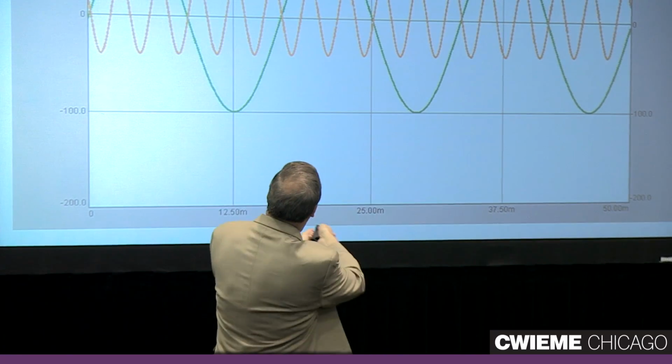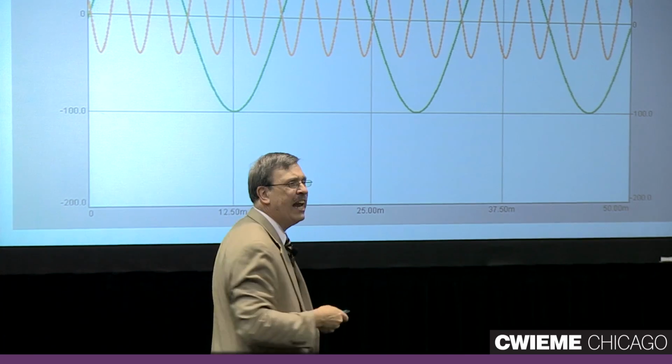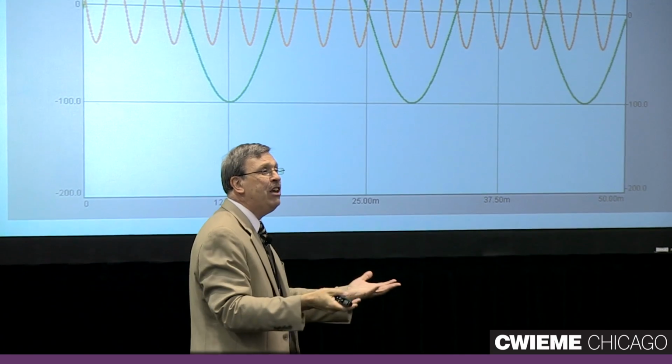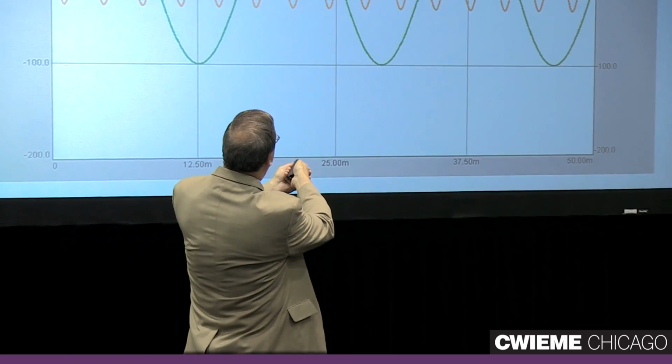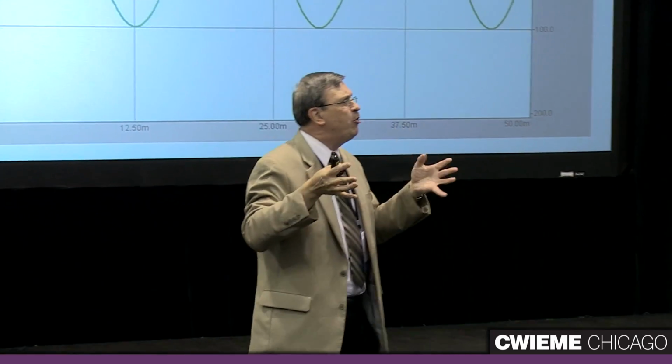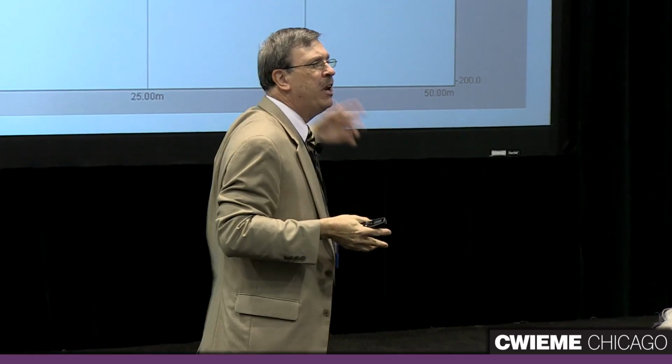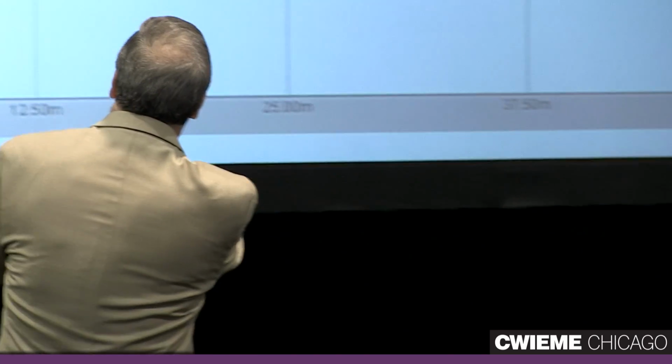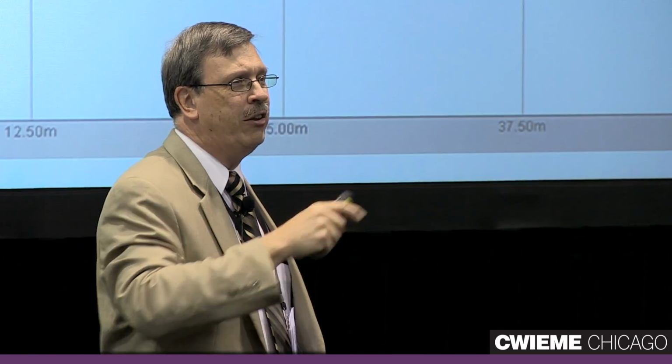The amplitude, we can see the peak of it, works out to be about 28 amps RMS. And for the phase angle, we say it's 153 degrees. It's sort of like, where is it within its cycle when the fundamental is at 0 degrees? So we have 0, 90 degrees there, 180 degrees there, 270, and then back to 360 or 0 degrees for one cycle. So 153 degrees is a little bit before you reach 0, but you're heading downward, and that's what's happening right here. It's at the 153 degree point right there. So that's a 5th harmonic.